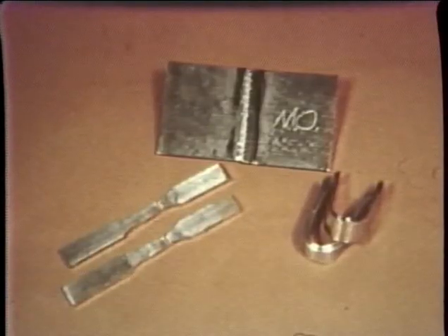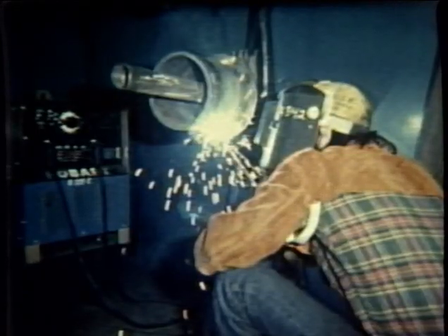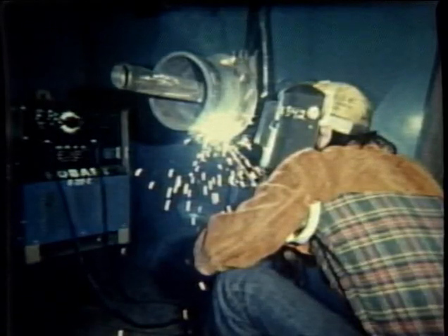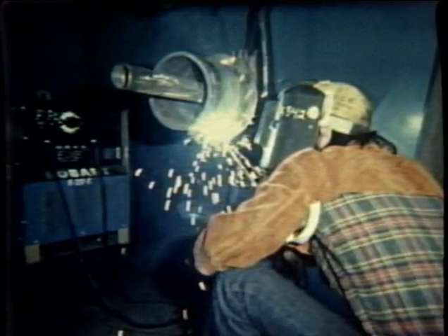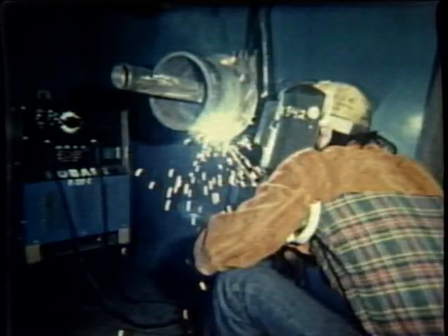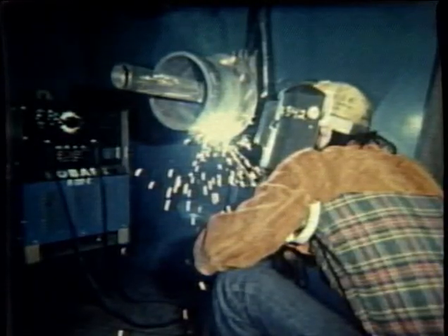Welding codes use a variety of destructive testing methods to evaluate materials so that design performance requirements can be met. These tests are also used to determine the quality of welds produced by specific procedures, so that the procedures and welders can be qualified.